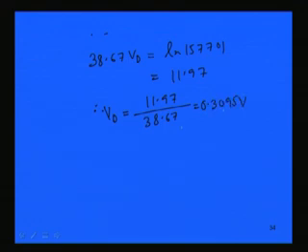Now, just notice that for 0.3095 volt we get 100 milliampere, but earlier for 1 milliampere we had to apply a voltage of 0.19 volt. So, even if we increase the voltage by less than twice, we are getting 100 times the diode current. For a small change of applied voltage, we are getting such a huge rise in current, and that is very clear from the characteristic curve also.